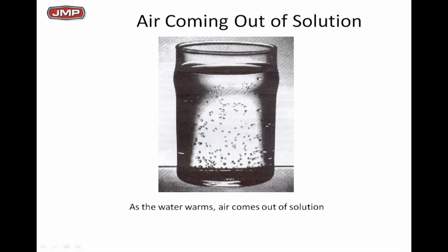So if you're taking pressure off of the water, is that cold water, that water is 60 to 70 degrees, sits on your table, it warms up. So you're warming the water up, driving air off. You're taking the pressure off, driving air off. So what does that mean to you? The lower the pressure and warmer the water, the more air you get out of solution.